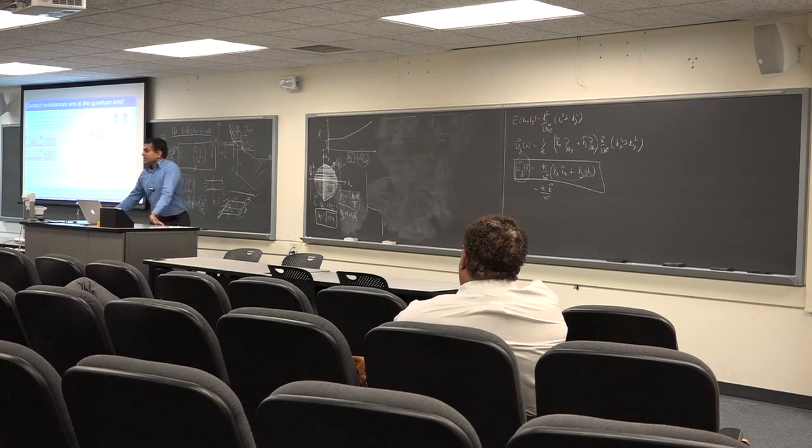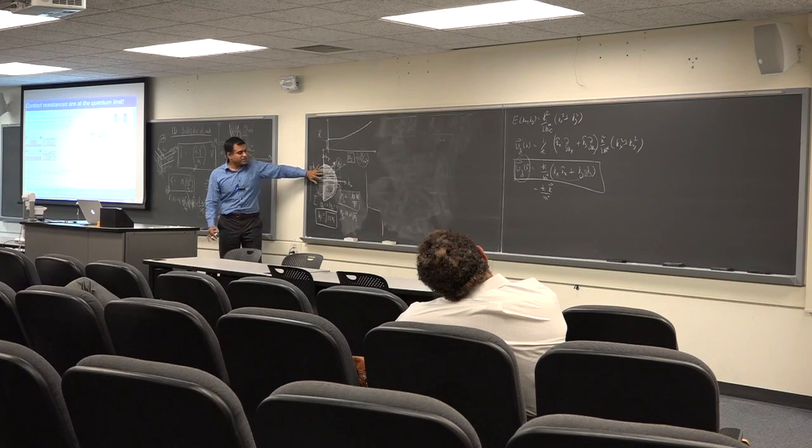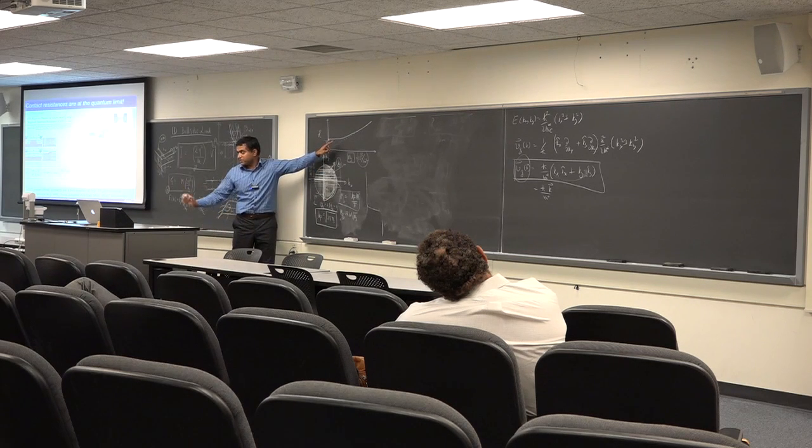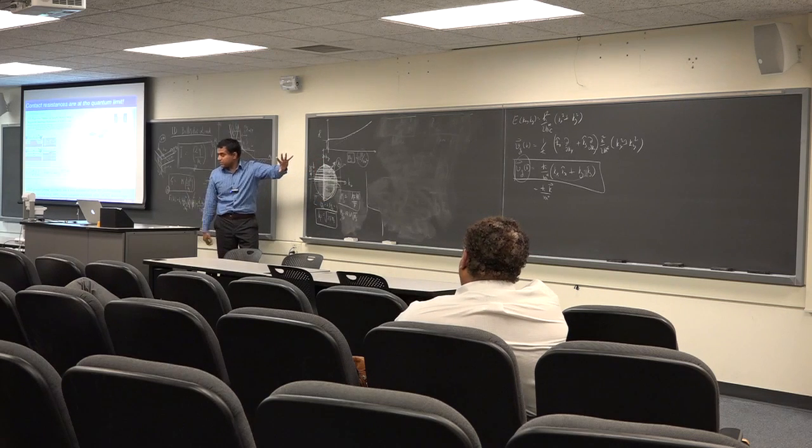And the second question is that you said the number of modes does not depend on the band structure, but I think the number of valleys will. So the number of modes, the moment I say that I'm going to put this many carriers, right? The k space is independent. You are absolutely right. You can see the number of valleys will appear here, right? So the E-k won't matter, but the number of valleys will matter if you want to find the carrier density. That's actually correct. So maybe I should correct myself: the shape of the band structure may not matter, but the number of valleys will definitely matter because there are g_v copies of this in k space. Absolutely, good point.